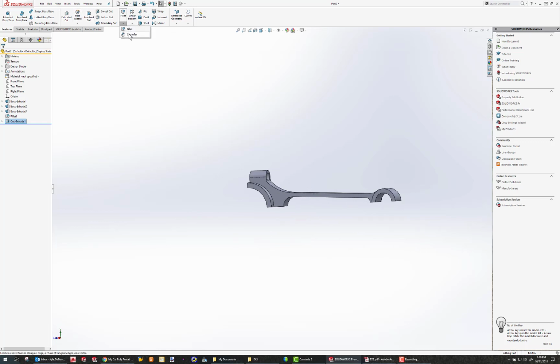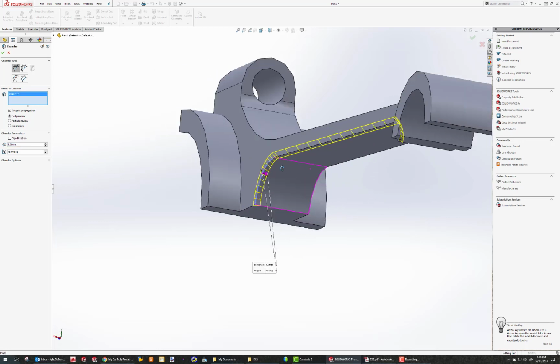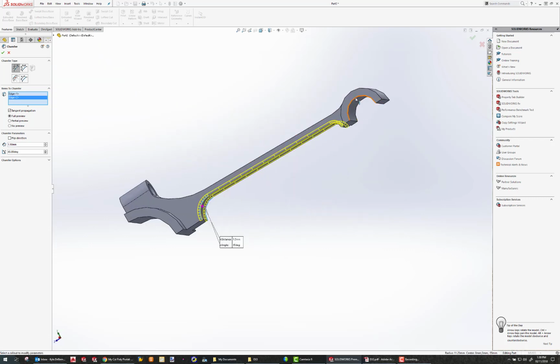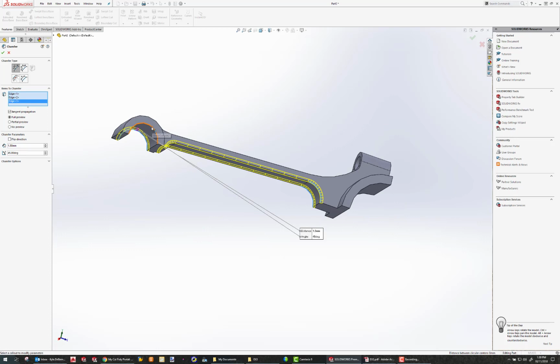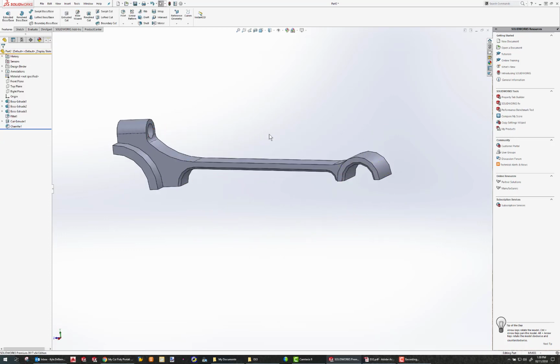Now I can come in here and do a chamfer. So the chamfer on this part is 1.5 millimeters by 45 degrees, and it occurs, if I click that start little curve there, it goes all the way across. I want to do this side. Then I also want to do that one and that one. So I get all my chamfers done in one feature. Okay, so basically I'm done at this point. I've done the entire top half of the part.